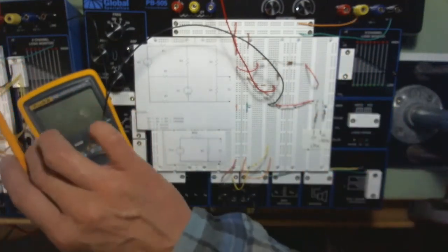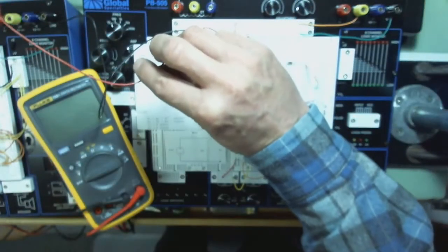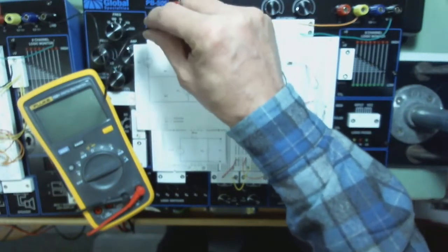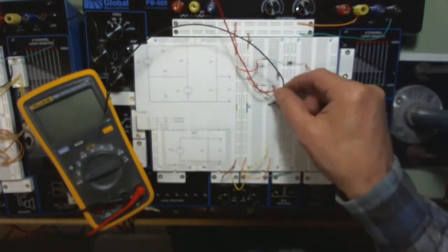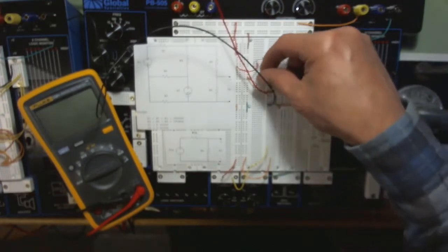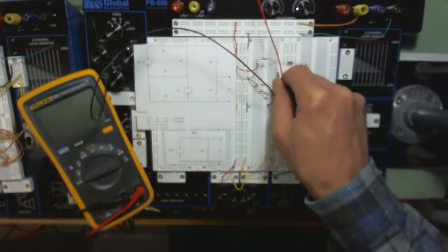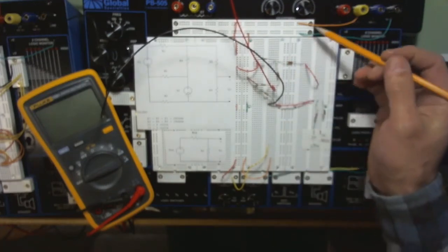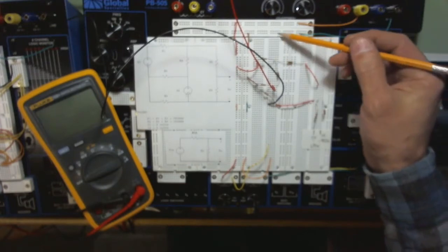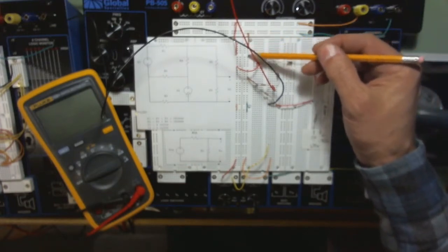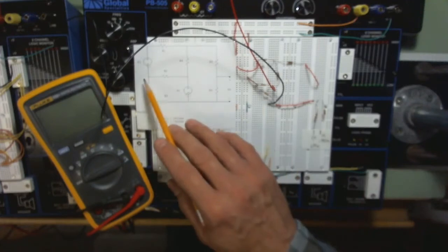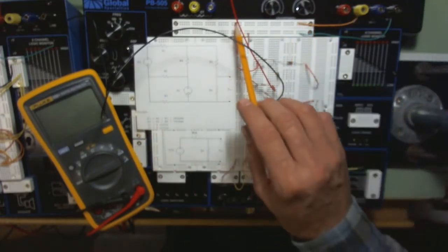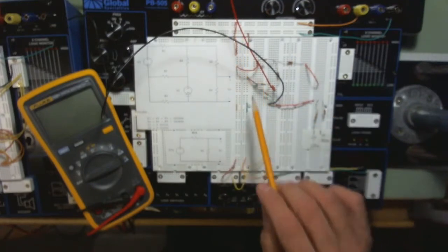There's one over here, and then I've got these wires. I don't know if you can see that one. This wire here, that's my +5, and this is the ground. Okay, so I've taken care of that. That's going to be my 5 volt source, and then my 9 volt source is coming from here. So there's the ground, and I'm using this bus bar coming down to here, and that's the ground, so that's that point right there. And then the plus voltage, that's right there. There's plus, and that's coming over to there.